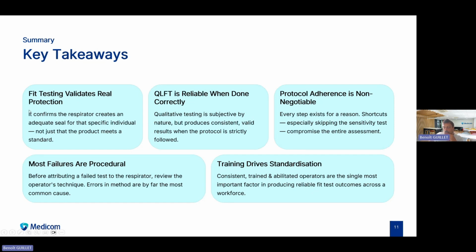So what are the key takeaways for fit testing? If there is one key message to remember today, it is that a certified respirator does not automatically guarantee protection. The CE mark on the mask does not automatically guarantee protection. Protection really depends on the quality of the seal between the respirator and the individual wearer.